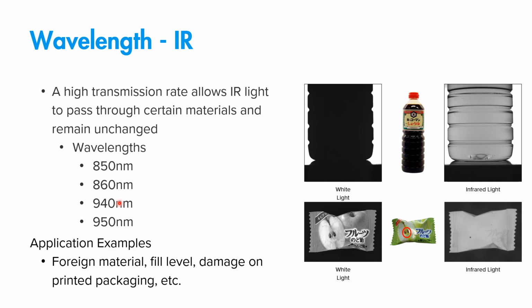But I want to know if I can remove the text or the print on this blister pack, for example. You can just shine the IR wavelength on it, and if the text removes, then you can assume, okay, the flatness of the dome light with the wavelength of the IR, I can get an IR dome light and my application will be solved. So that's why form factor isn't as critical, but having a good variety of wavelengths is more important.